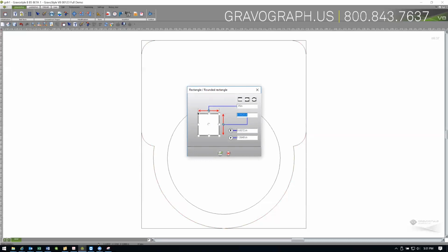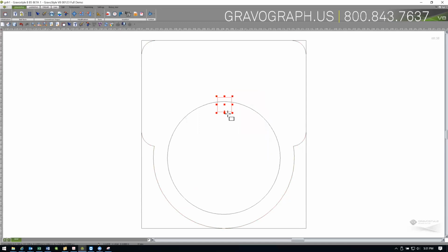My drawing is in millimeters. We can see that my software is working in inches, but if I put in that I need a 3.96 millimeter and give it the mm, then it will make the calculation for me and draw the appropriate size tab.